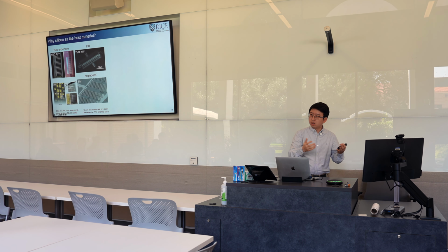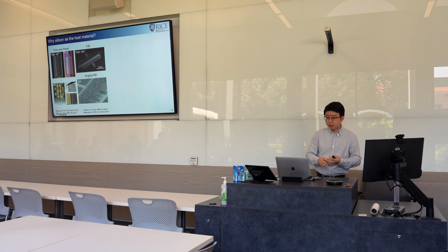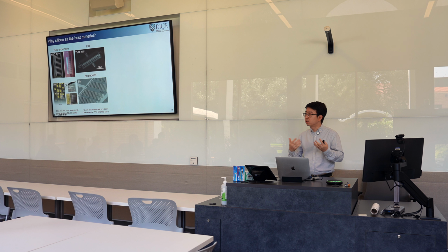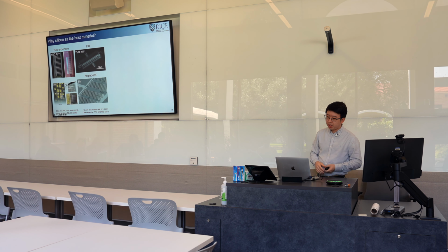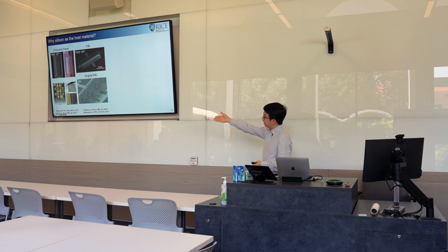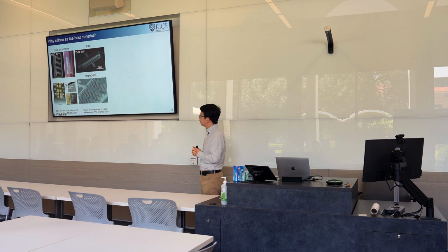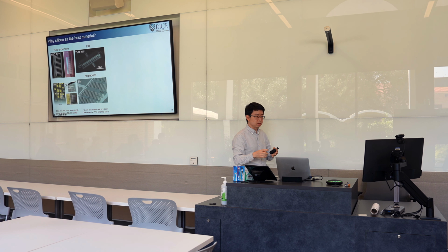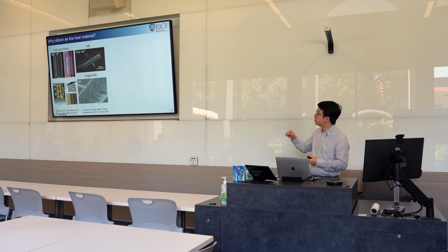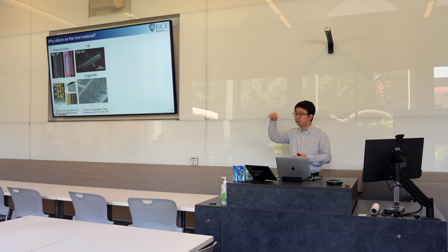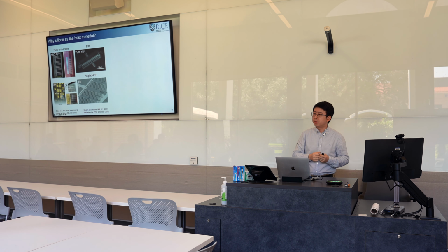For diamond, there are a few very promising quantum defects. People have developed similar techniques, for example, this pick and place. On the lower left side, this is called nitrogen vacancy in diamond. What you can do there for device integration is to fabricate this diamond quantum circuit and then use a so-called tungsten tip to pick it up and put it on another aluminum nitride-based nanophotonics circuit, okay?